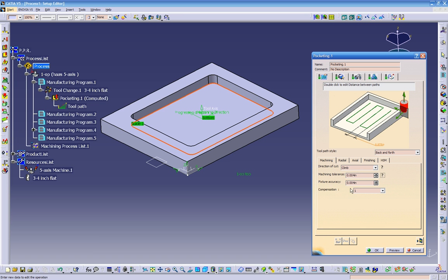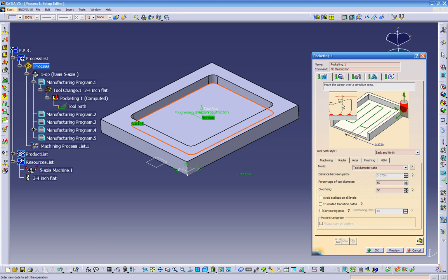You can see over there. Radial is asking us over here for the tool diameter. So you just put over here a kind of step over. Right now it's 50%, so the step over ratio is 50%. Or we can put a distance. So right now we'll put step over .375. Step over from here to here, we get .375. Or we can put the step over ratio or maximum distance. They show you right here the difference. But I like ratio the best, 50% of the tool.